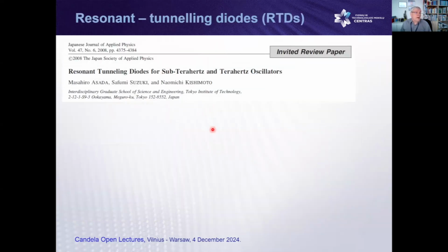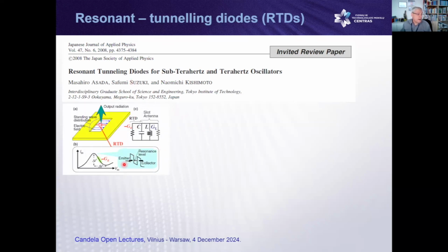So, resonant tunneling diodes, look at the papers, an absolutely elegant device, and I took one of those important papers in the field, and they have very nice operation here. And the main idea is to go to this so-called negative differential conductivity regime. It means with the increase of voltage, the current decreases. It means if I calculate, the power becomes negative. In physical terms, it means generation.